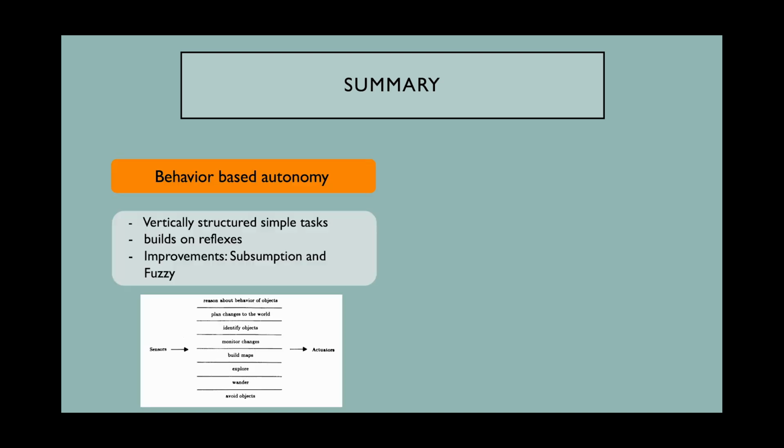Let's come to the end of the video and provide a concluding summary of the topic: behavior-based autonomy and intelligent rover architectures. Basically, it can be said that behavior-based autonomy lays the foundation for the methods of intelligent rover architectures presented here. The behavior-based autonomy moves away from the classic horizontally structured processing chain of the robot towards a vertically structured and parallel operating chain that doesn't require modeling of the entire system, making it more computationally efficient.